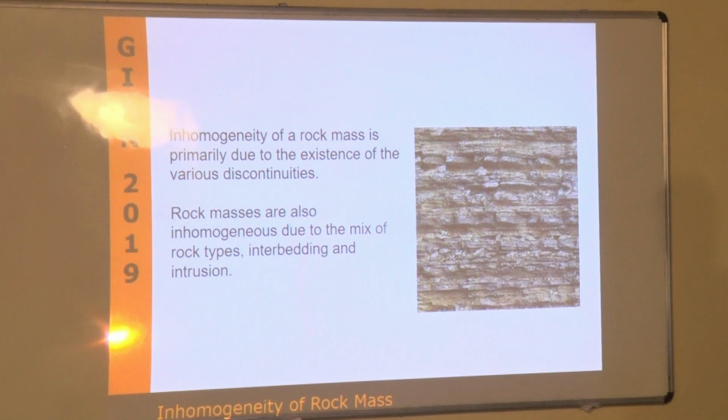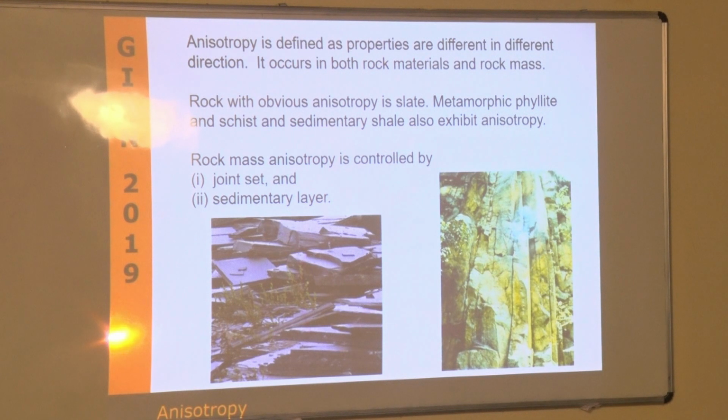So the rock mass is something like this. This is just a nice picture of how the rock could be, and it's not homogeneous. Very often there are fractures, bedding planes, schistosity planes that create anisotropy, not just on, for example, the sonic velocities, but more importantly, probably, on the mechanical response.